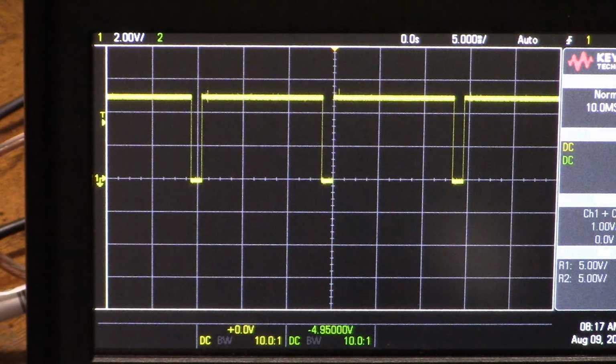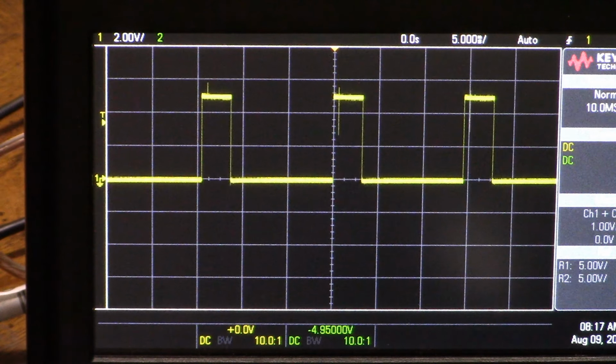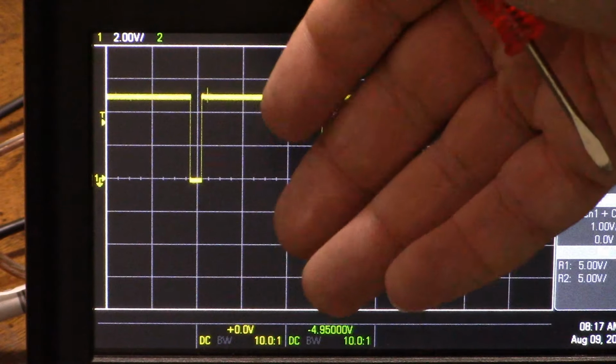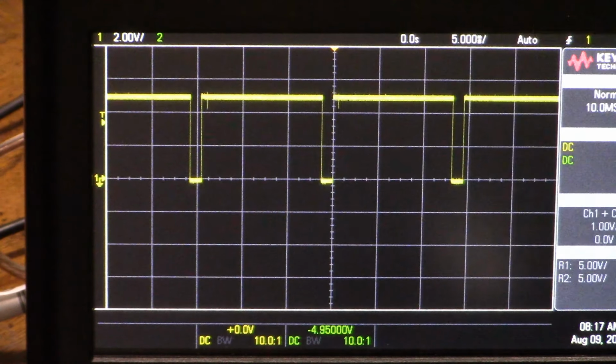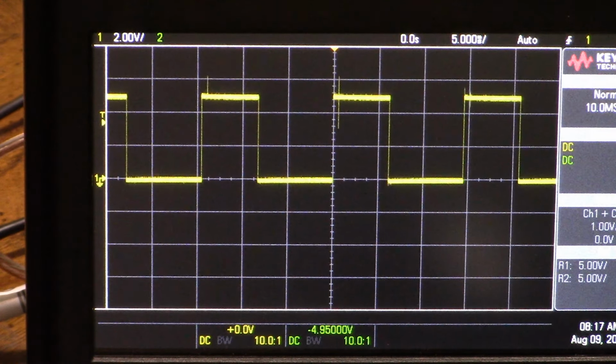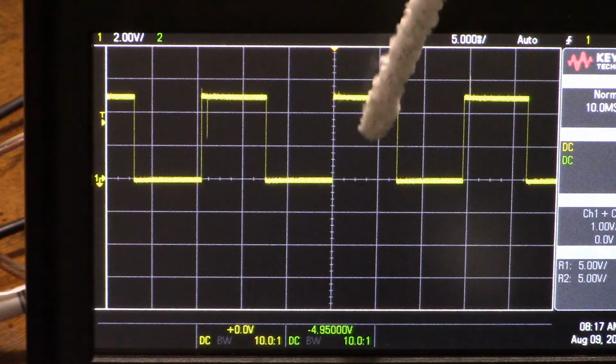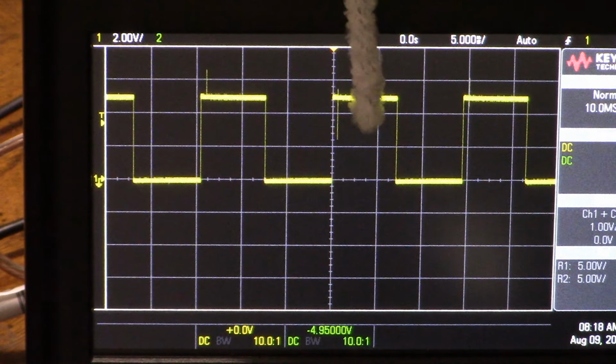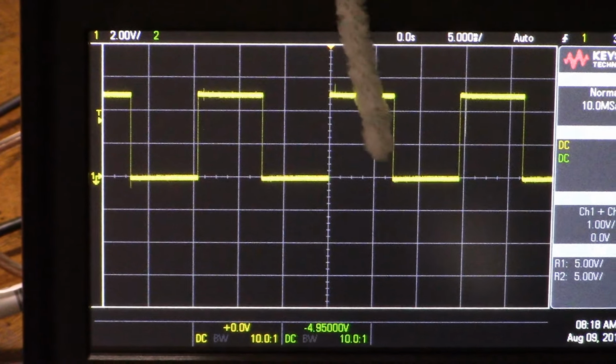But that's all it is. Super simple circuit, and all I'm doing is changing the voltage on the control pin of the monostable, and I set my duty cycle. So that's how you set it if you want a live controllable PWM. But if you just want your nice 50% duty cycle, hopefully anybody watching the video hasn't gotten sick of waiting for me to get to that point, you just set it at 50%. You can pick any duty cycle, including 50, or whatever this roughly is. So whatever you want for your application, 2 timers, and you get your nice square wave. And that's all there is to it. And for safety, I will turn everything off.